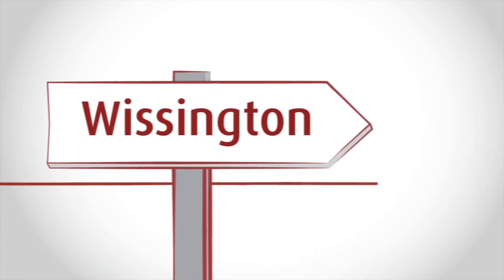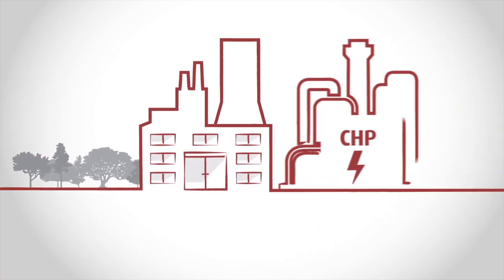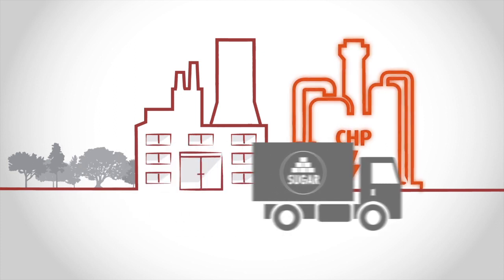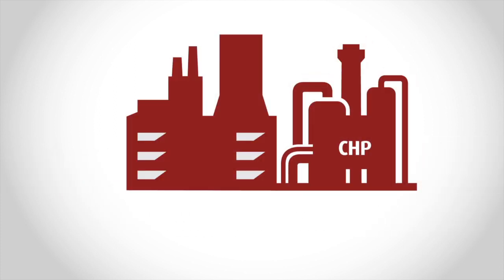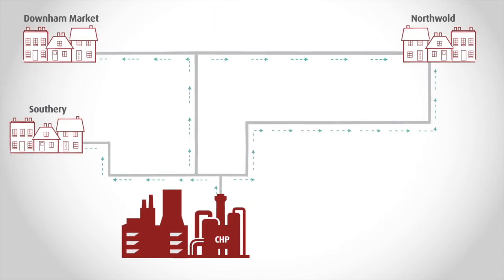Wissington in Norfolk was an area with a capacity problem. A factory there wasn't able to maximise the generation capacity of its CHP plant because of a constraint on two parallel circuits feeding the factory. The line from Wissington to Downham Market is shorter than the other. As a result, it got overloaded before the generator was at its highest output.